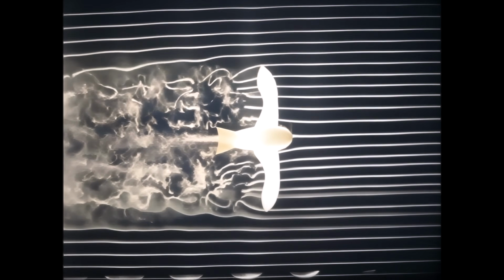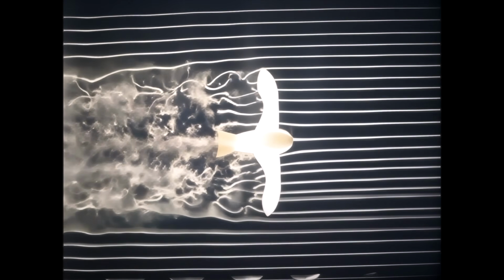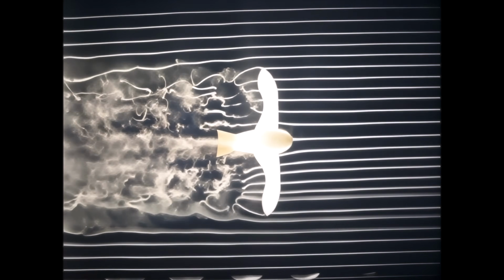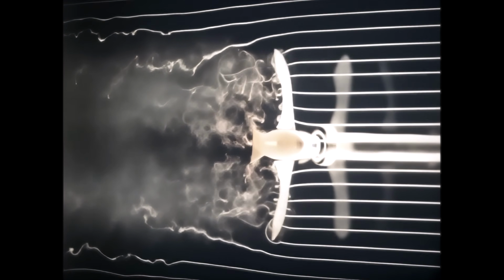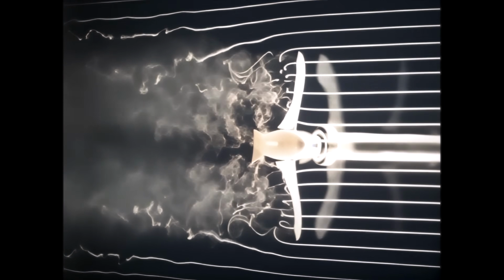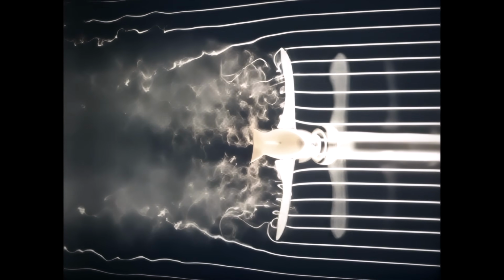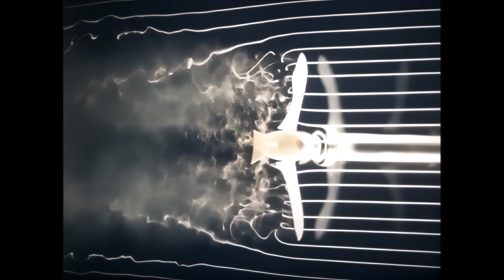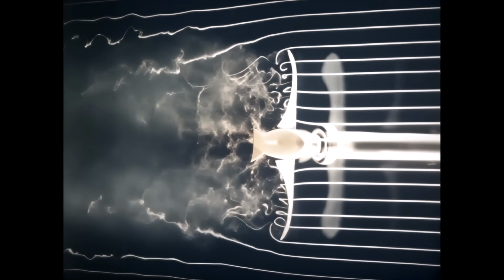You see, since we oscillate the wings, the flow behind this birdie is also pulsating. And we see that while it beats down, every time a tip vortex is generated. While when we would have steady wings, then this tip vortex is a steady vortex. But here we have a row of single vortices emerging from the tips of the wings.